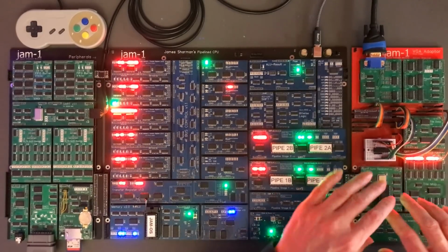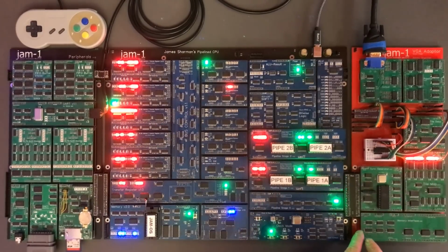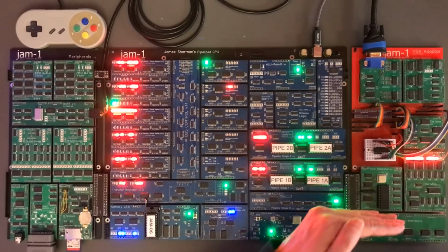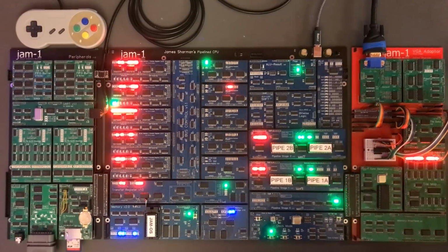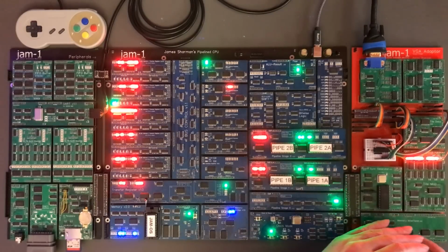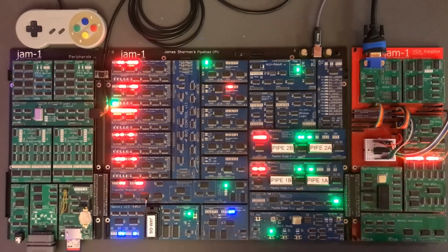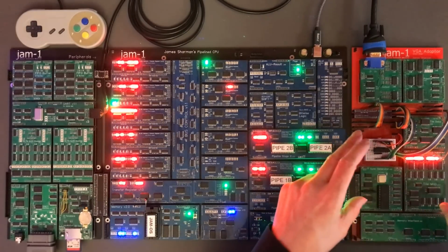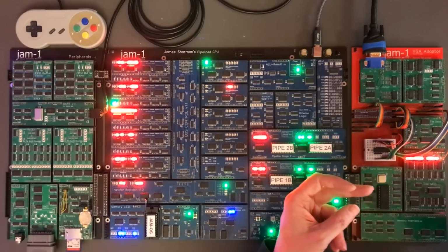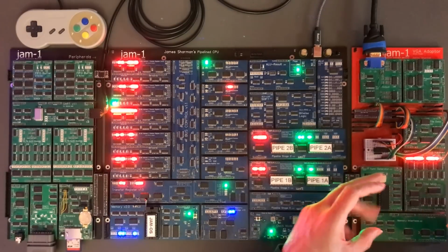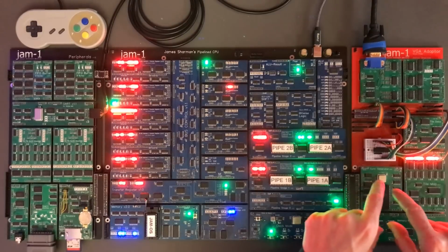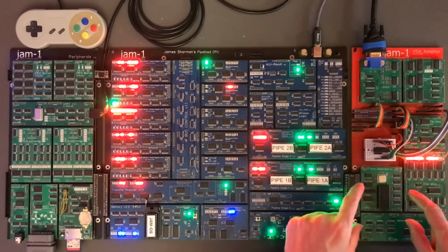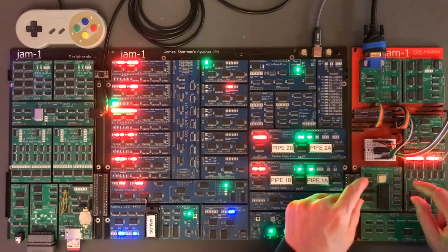I've also got a memory map. So I've got the address decoders here that define the way that different segments of memory, the palette data, the tile map, and I've already got some reserved lines for sprite raster data, but the addresses of those, the sizes of the regions, I've kind of revisited in my mind a little bit. Specifically, I put aside 4 kilobytes for the sprite data, and I'm going to drop that to 1 kilobyte.